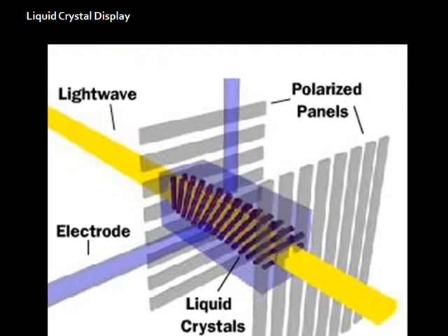When voltage is applied to the liquid crystal, it twists in direct relationship with the applied voltage up to 90 degrees. The more the liquid crystals twist, the more light from the backlight or reflector is polarized to match the polarization of the front glass, making the pixel lighter toward the off state.